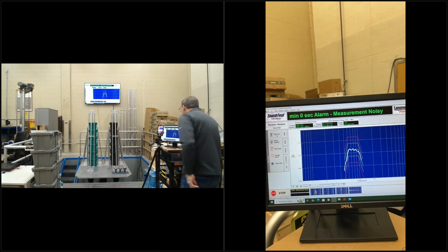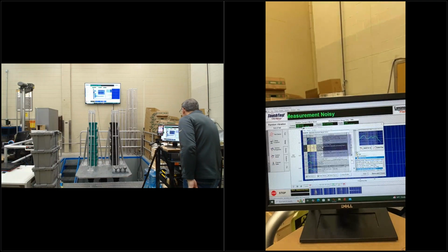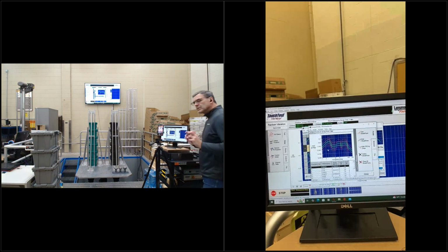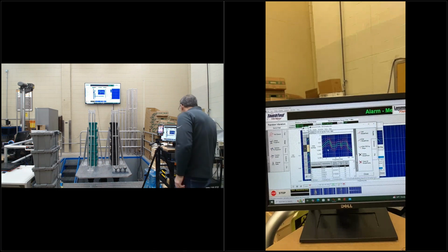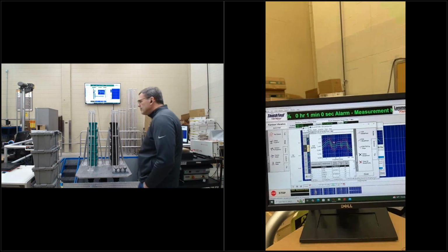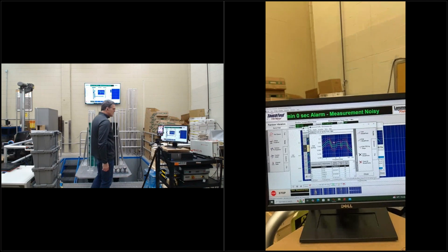Like a leaf spring profile, if I go back to my test queue and load this one up here, if you can see this on screen, this is pretty normal for the shape of a leaf spring truck profile. This is 1 hertz, 2 hertz, 3 hertz, 4 hertz, and then it drops down. But the key low frequency content is in the 3 to 4 hertz range. Then it drops a little bit, and comes back up at like 16 hertz. You would not want your unit load to have a resonance.